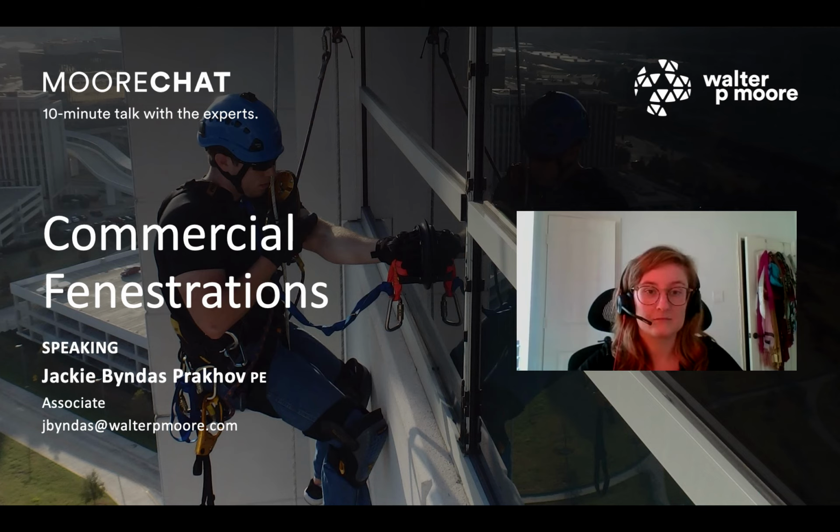Jackie, I had a question as well. Do certain areas of the country favor stick-built or unitized curtain wall systems? That's a great question. So typically, as I said, in areas where labor costs are cheaper, they may go for a stick-built system, just due to that fact, but unitized systems are definitely favored on the West Coast or in seismic zones just because of the way they can accommodate movement.